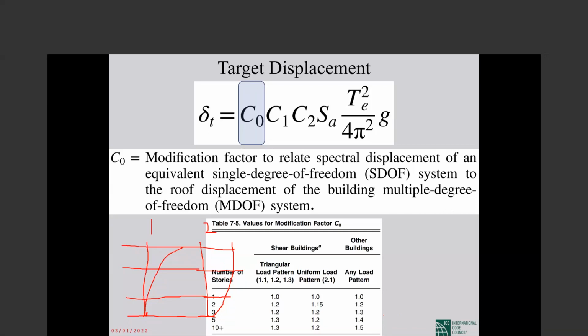This is the general type of behavior of the building as a whole, not of their elements. So for the multi-bay, multi-story frame, the elements undergo flexural deformation, bending deformation, but the building shows shear.